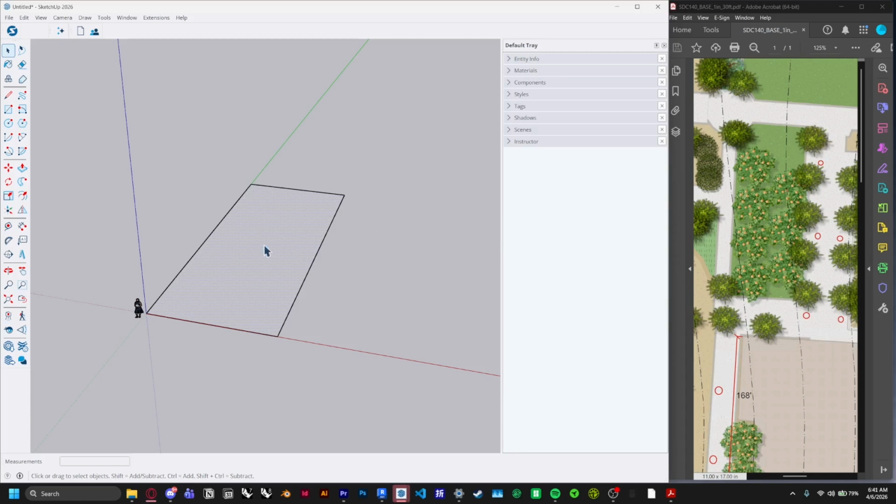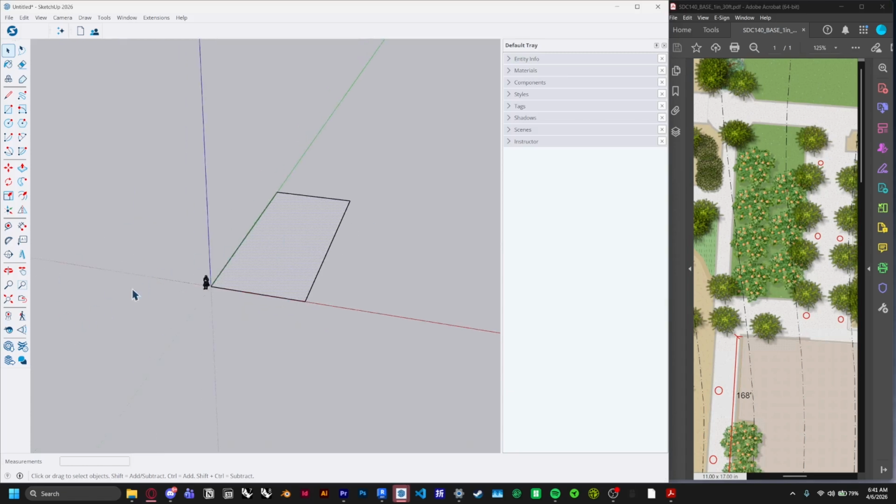Also, there is a slight slope across the actual, flat part of the site. It's about 2 to 3 feet, but we won't be modeling that to make it easier on us. We are going to be modeling the slope next to the road, along with going up Thompson Flats, but the actual slope of the site will not be modeled.